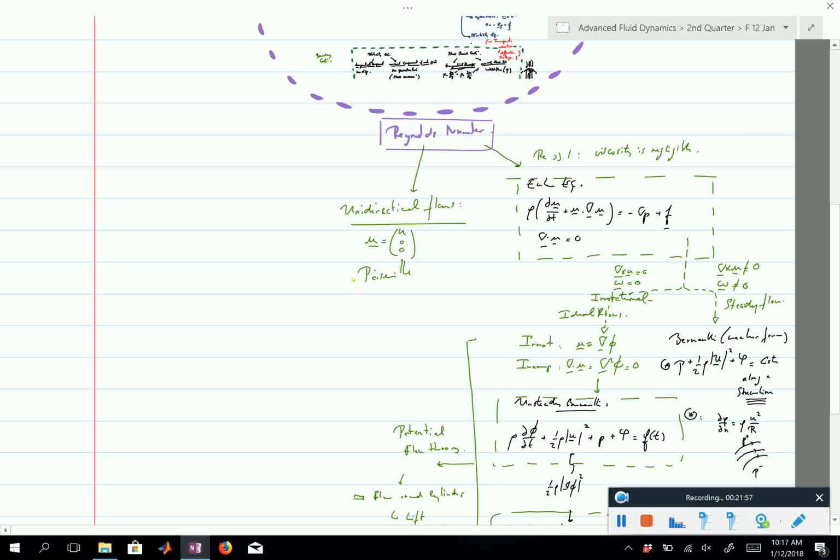Poiseuille flows and Couette flows. Those are the two biggest examples of unidirectional flows that we discussed. I would definitely have those flows on my cheat sheet. Poiseuille flow: the velocity distribution, the average flow, the volumetric flow rate, all of these we derived in class. A very simple example would be to rederive that, but most likely this is assumed to be known, right? So you need to know that, and then the friction coefficient associated with a pure Couette flow, we also discussed that. So these you want to know.